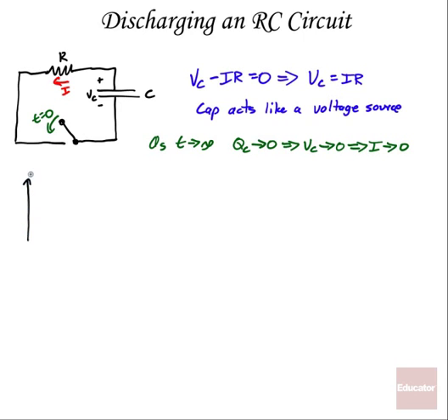So if we made some graphs of what we have going on now, let's start with current, I versus t. We start off with the full current, and over time, we're going to bleed off that current and approach 0. And guess how long that takes again? About 5 tau, till you get to 99% of the way to your final destination, or here in this case, 0.